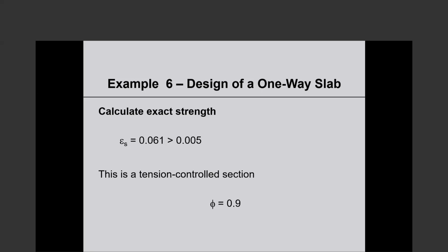So in section 6.3.2.10.4.1 of BNBC 2020, there is a coefficient for flat plate, and that coefficient is 0.25 Ig. What would be this coefficient for beam slab? It's very specific.